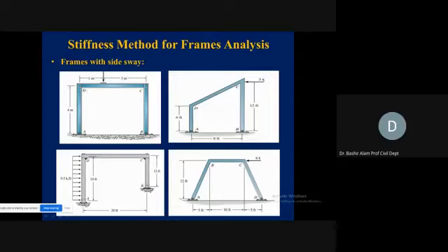Whatever displacement you have at D to the right, the same displacement you will have at C to the right. If it is to the left, then at both it will be to the left and by the same amount. So in this case, the lateral displacement is because of the unsymmetrical loading.